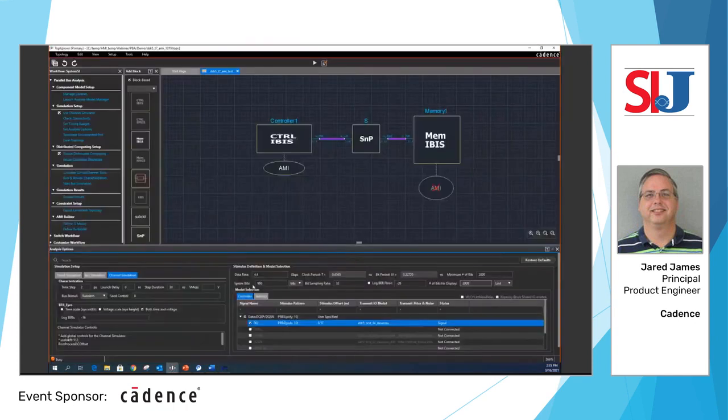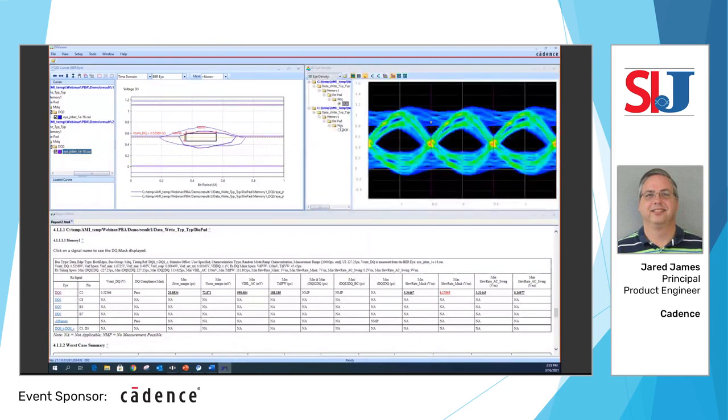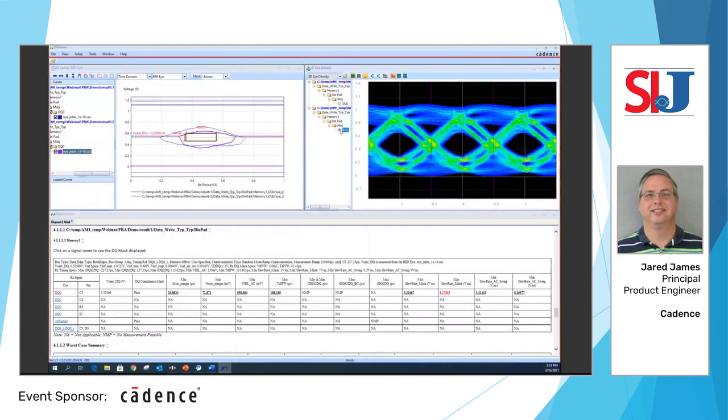So what happens if we go back and change this to 6.4 and run the simulation and see the results from there? Let's see how much additional bandwidth we have on this particular circuit. Maybe we can run our memory faster. That simulation was already run previously, and we can look at our eye plots there and here.